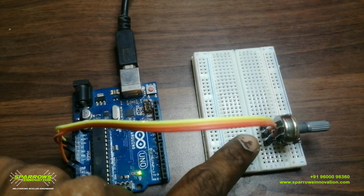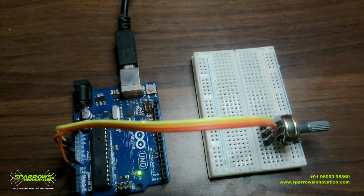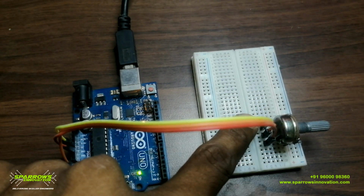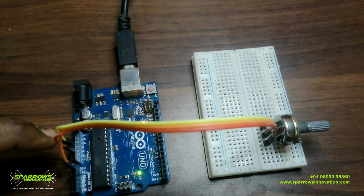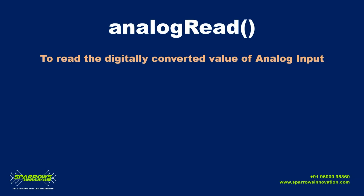So now we finished the connection. The top pin is a 5 volt and the last pin is a ground, and I have given the center pin to my A0. So we can program now.